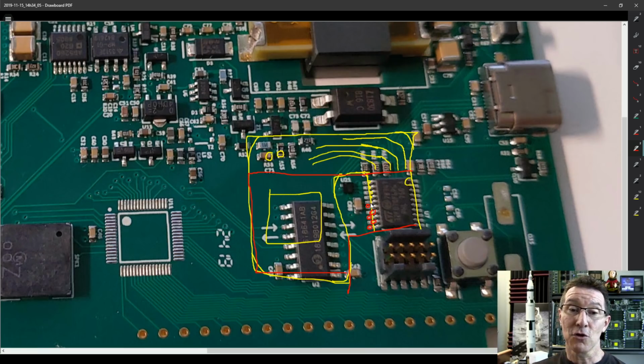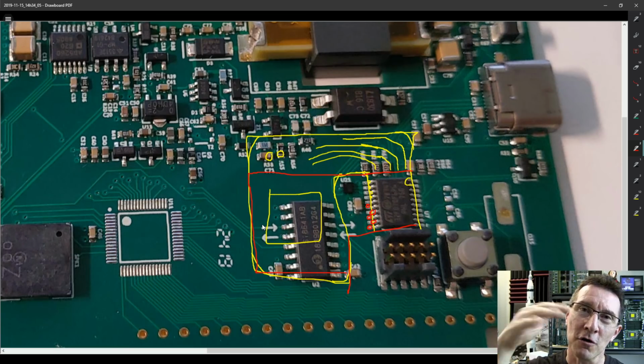So anyway, that's the story behind what we're doing today. We're going to manufacture a flex, manufacture, that's a new word, I'm going to run with that. We're going to manufacture a new flex PCB, just a mod PCB that literally has just the one chip on it plus a pad to solder down onto the top of this chip here. And you would design this like you would any other PCB. There's nothing special about flex PCB design here, unless it does actually flex. And then, as I said, you want to use curved traces.